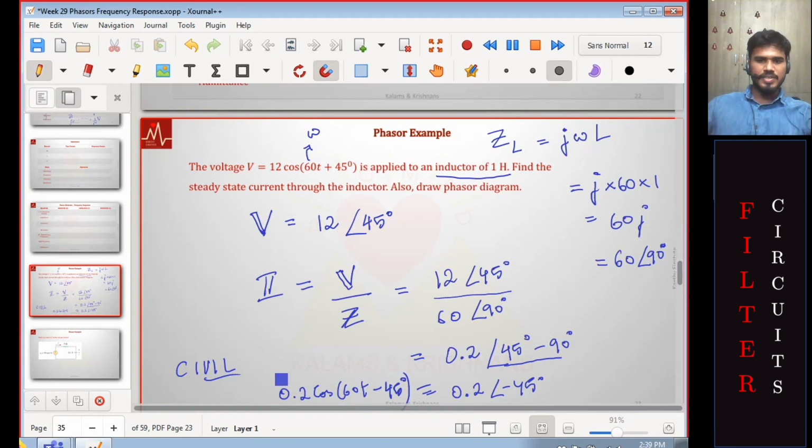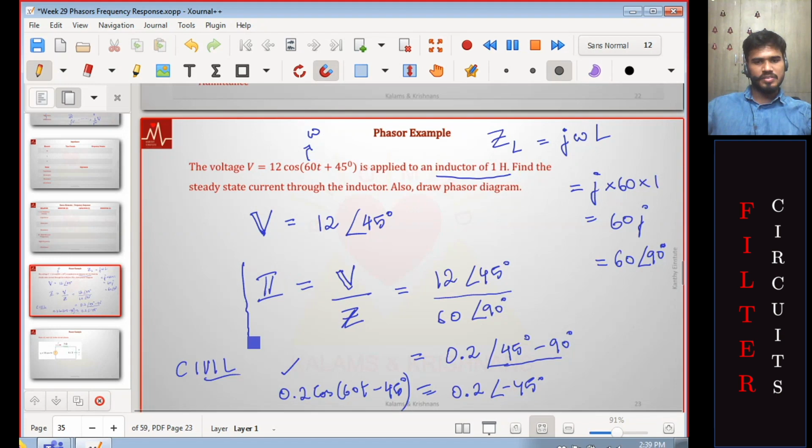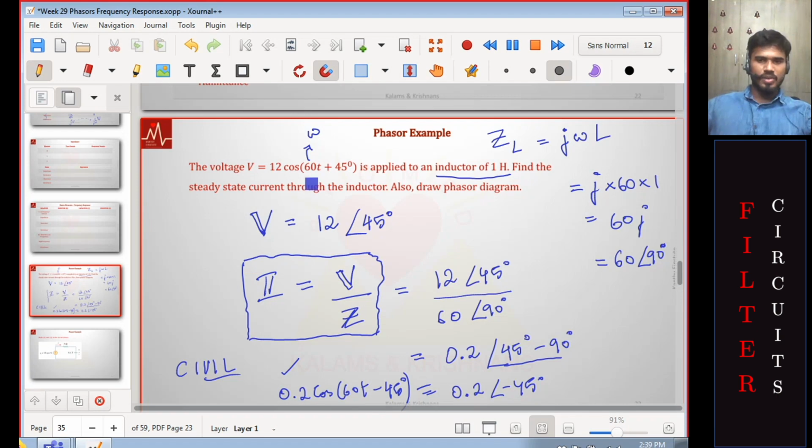That's it. You got the answer just by applying V is IR. There is something like resistance even for AC circuits. If you're looking at one particular frequency, you can write the V is IR relation and get answers easily. And this is a simple example, just one inductor, that's it. We are not even talking about a network yet, but all the principles apply.